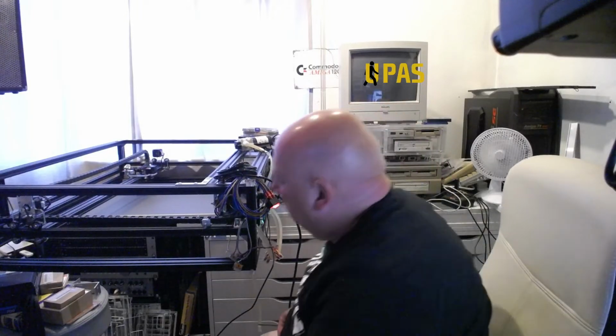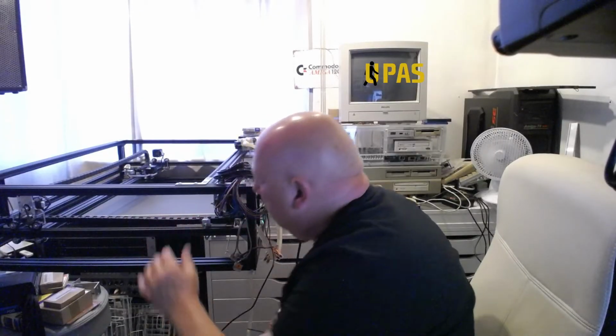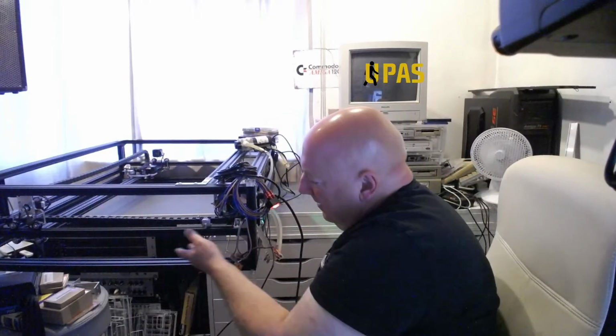I know they don't do the 5,000 anymore, and even Okay, maybe that'll stop it, because when it comes back it starts to sag, and then it kinks and it locks the thing up. Right, let's try it again. Right, that moved okay. Ah, real progress now, yeah. See if it can go a bit faster. Oh, it buzzed then. I heard it buzz. Didn't like that. I think I might have to go. If I want to go fast, I might have to go to bigger stepper motors.